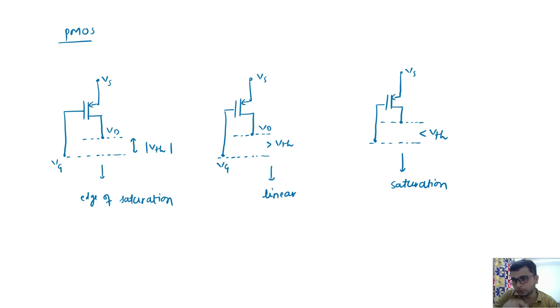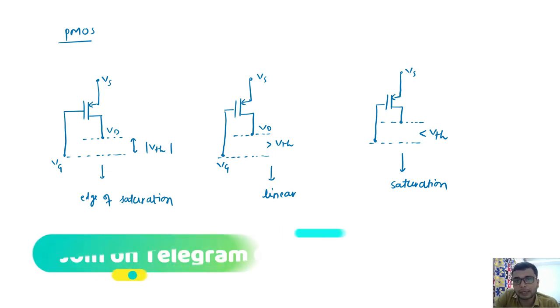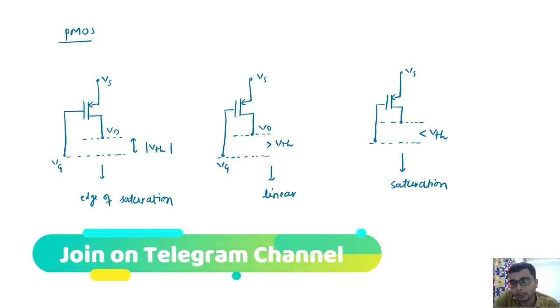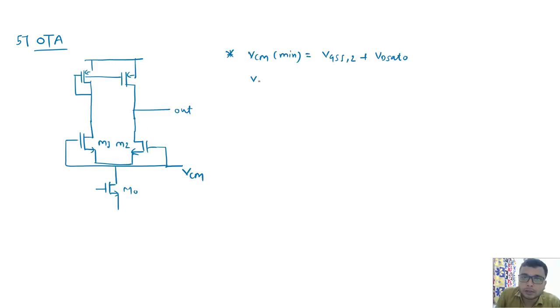This thing we will use in the structure, because the 5-transistor structure is simple, so we can easily calculate the input common mode swing. So what input common mode swing came for the 5-transistor OTA? What is the swing for this input pair? This is the maximum and minimum value of our common mode that you can see from here. So these are the minimum and maximum values.